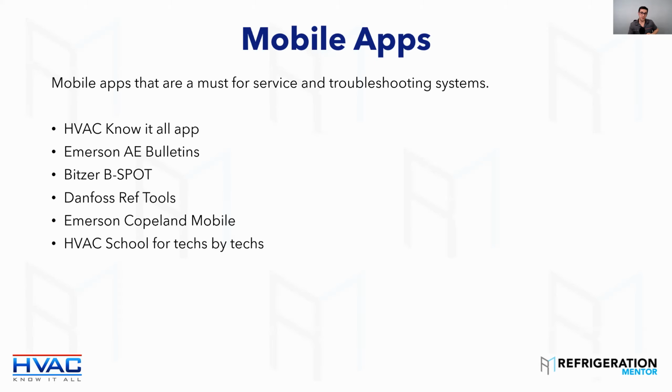You got to go to the performance chart for that compressor. It'll say on the right hand side, performance feature, and then go into full performance or dynamic performance and put in your conditions, and it's going to spit out what your discharge temperature should be. Pretty cool app. So yeah, that's wicked. Play with it a bit more. Play with all the apps.